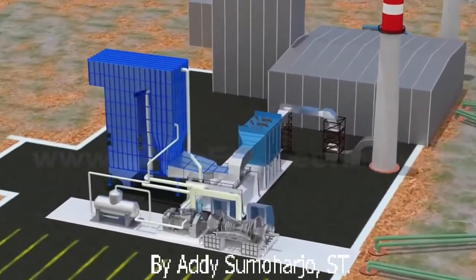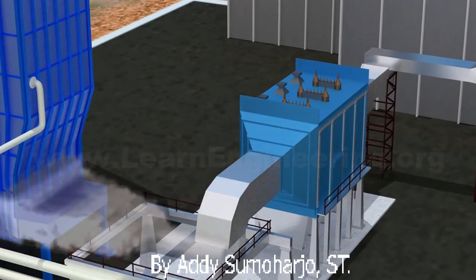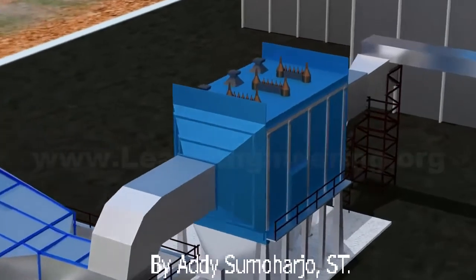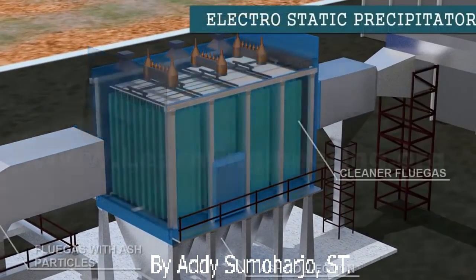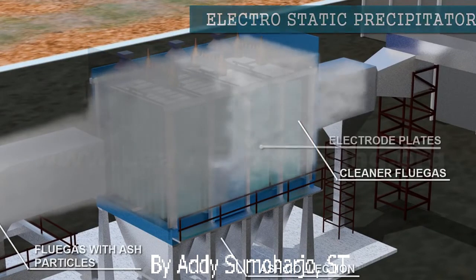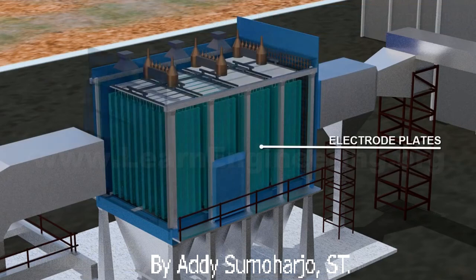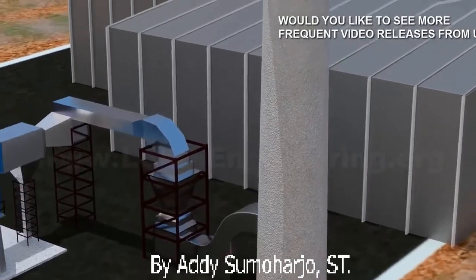At the heat addition side, the burning coal produces many pollutants. We cannot release these pollutants directly into the atmosphere, so before transferring them to a stack, the exhaust gas is cleaned in an electrostatic precipitator. The ESP uses plates with high voltage static electricity to absorb the pollutant particles. We hope that we've given you new insights into the